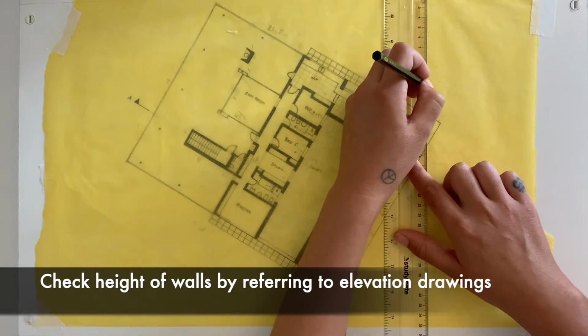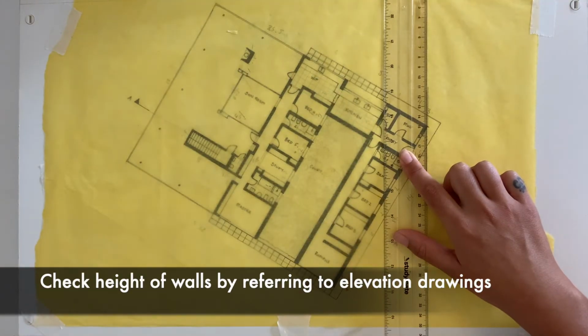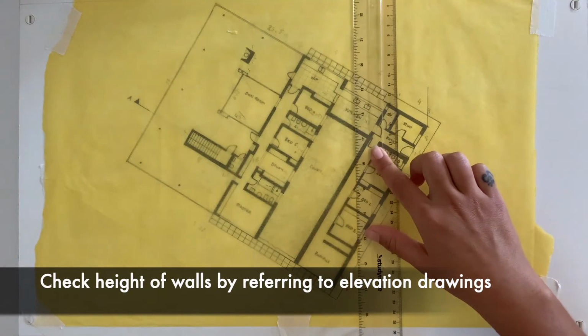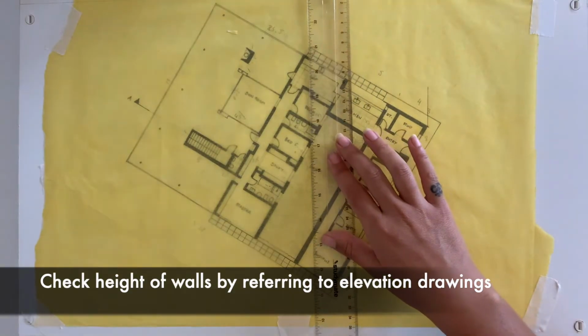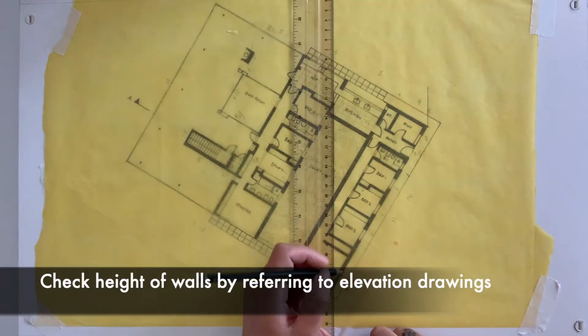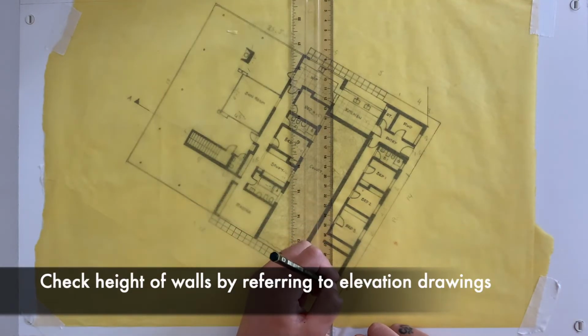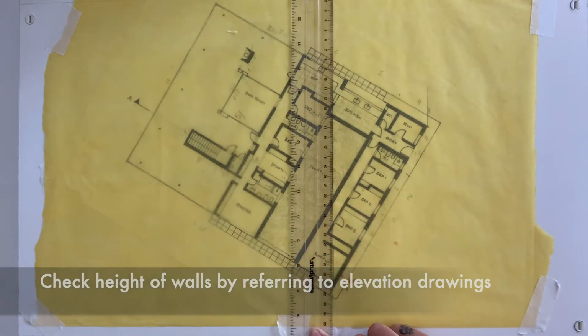So we're going to project this floor plan into 3D, and to do that, we are going to add height to the walls. These walls have certain heights, and you'll need to be referencing the elevations or sections to this floor plan. So let's just say that this wall is 4 meters in height. You'll then have to scale it to what the floor plan is scaled at.